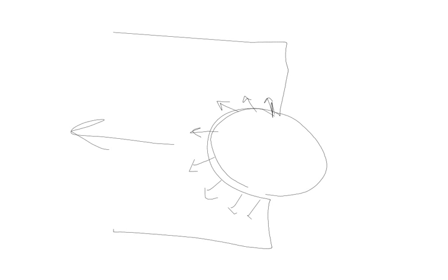That pin that sits here is pushing against it. So basically there's a bunch of forces from the pin pushing against the hole. Now, why is it only half the hole? Well, because if the pin is being pushed that way, then it's going to push right against that half of the hole here. The other half, you actually get a tiny bit of gap. So there is actually no contact between the pin and that second half of the hole. So all the pressure from the pin pushing on that hole is on this left side.